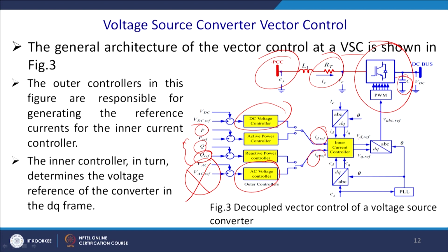And then you have an inner current loop, and that has to be very fast, operating close to the switching frequency. So you got a PLL, then you convert from the DQ to the ABC frame. Ultimately from the PLL you generate theta, and that logic you feed to the PWM, and again the theta you are getting, you can reconvert it from ABC to DQ, and also compare what current you are getting, and thus it will be a closed loop operation.